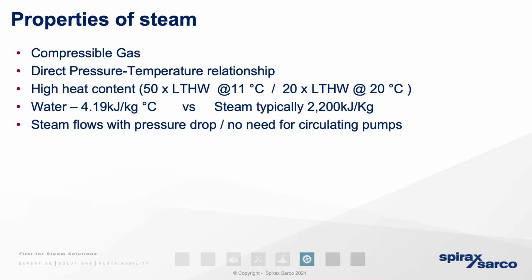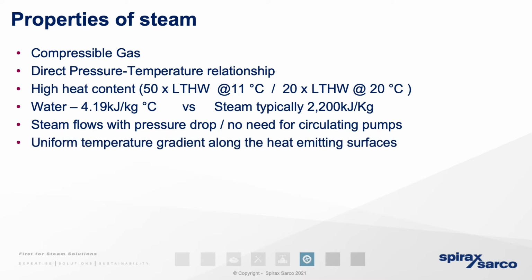We also know that steam flows due to a pressure drop at the process. In other words, we don't need distribution pumps in order to circulate steam around the system. And we also don't need to divert away excess thermal energy from the process, like we would with a liquid-based system. Because steam is a gas, it fills the heat transfer space in a very uniform manner. That means it transfers its heat energy very evenly across the heat transfer surface. We don't get those cold spots, striation, and other process temperature issues that we might experience with a liquid-based system like hot water.